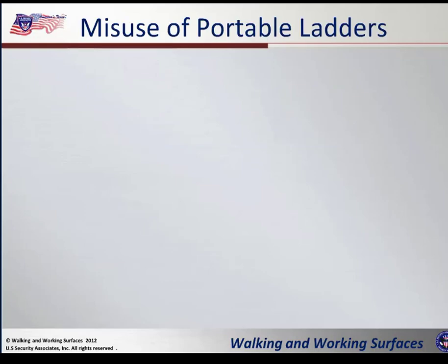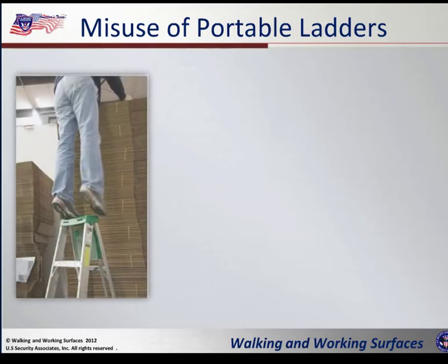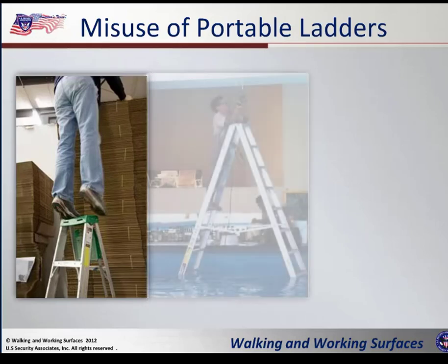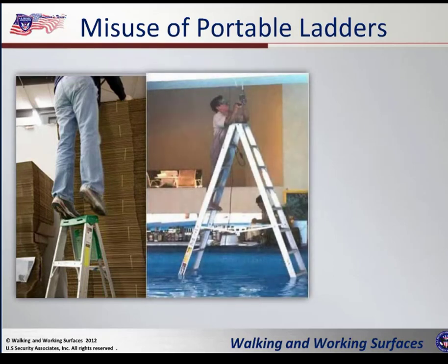Okay, let's take a look at some pictures of some people misusing portable ladders. Remember what I said? You cannot use that top step as a step, so please do not use the top of that ladder as a step. Also, look at what this guy's doing. He's barefoot using a metal ladder in a pool trying to fix an electrical light.